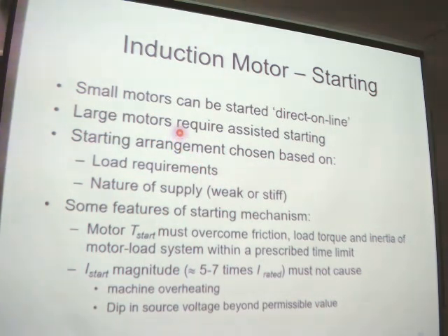We have just mentioned the method of DOL, direct online. Just connect the terminals of the motor to the power source. It's usually used with small motors, because for small motors the starting current will be small too, so it will not influence the power source.